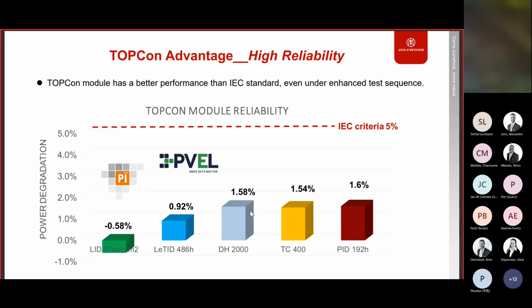Here is the advantage of TOPCon: high reliability. We have to do many tests according to IEC standard, and some tests are even enhanced test sequences. For LID, light-induced degradation, we find that for untapped TOPCon modules, after this test, module power is not decreased but increased. Increased 0.58%.